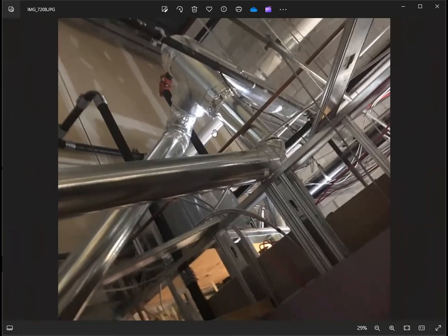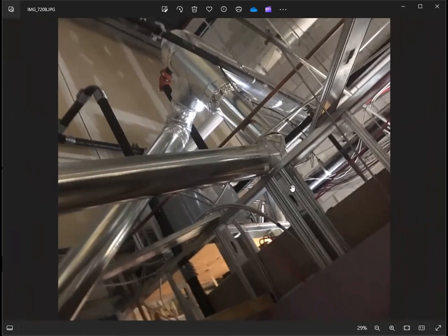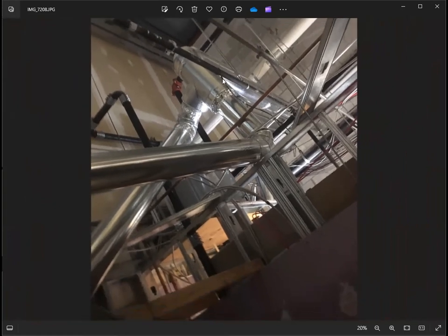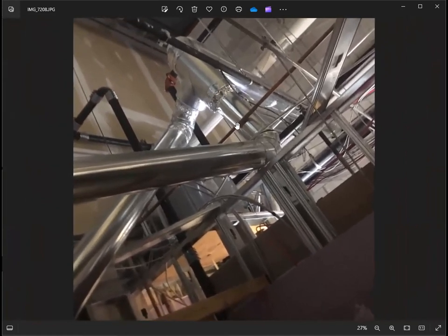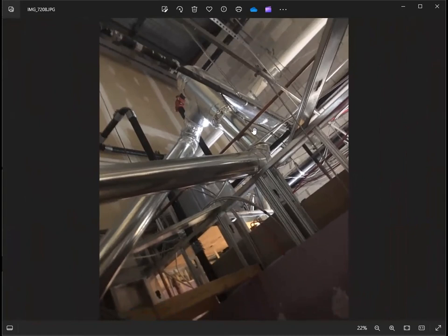I don't think this is acceptable. You could tell the contractor to have a hanger support from the top and hang it properly, because in the long run, this system will be right here for the next 10, 20 years. So it's not acceptable to have an installation without a proper support.